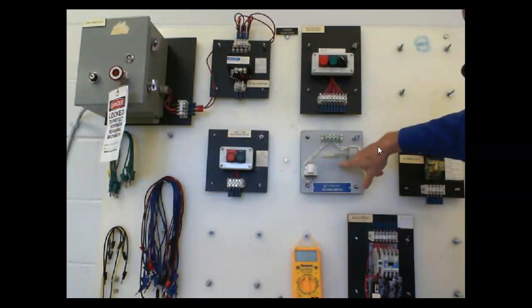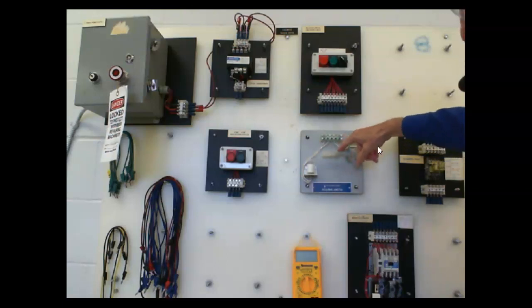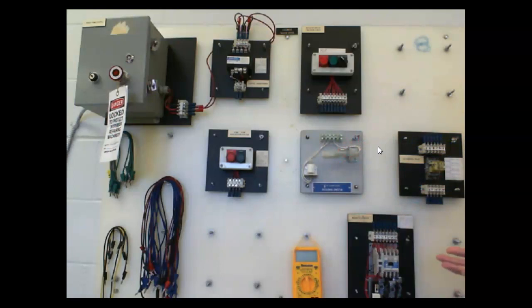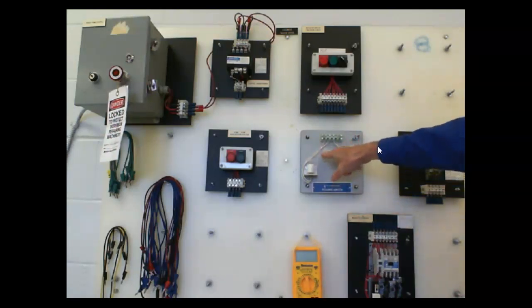So here's the liquid level switch we're going to start off doing. You probably can't see it, but here's the permanent magnet in here, and then the reed switch is here. So this would be normally closed. Right now, without any liquids or anything, it would be in this situation right here. And to make it de-energized, I just move this up.